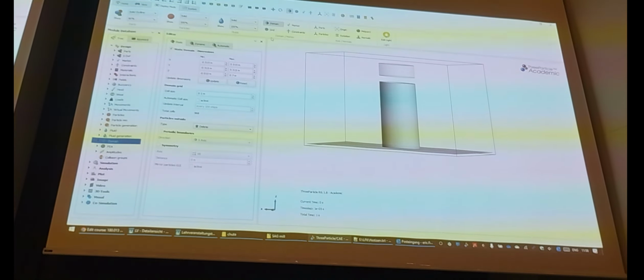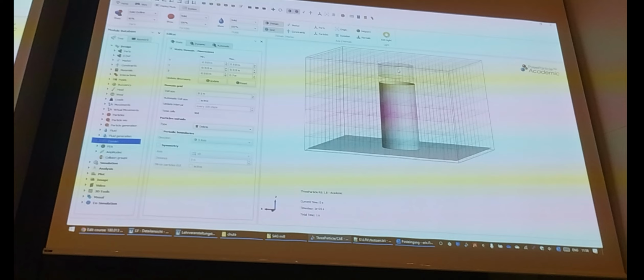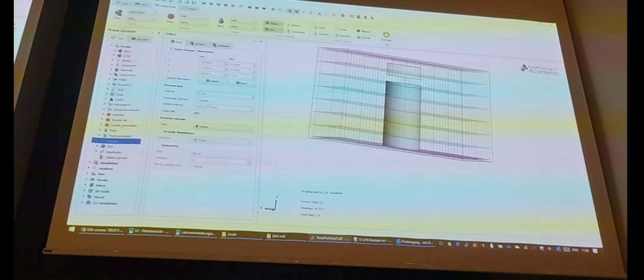What is the cell size? So here, you can see that this is the cell size. And I also do not want to exaggerate that because this is a science for itself, the appropriate setting of the cell size. A good rule of thumb is to set the cell size in the area of the size of your smaller particles.